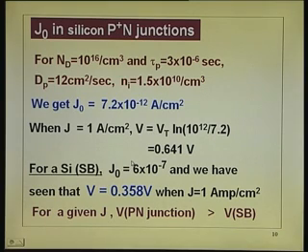So, cut-in voltage is a concept which is used by circuit engineers for convenience, because in the normal range of operation, that is the voltage across the diode. That is about 0.6 volts. That is the implication. So, people who are cautious will say 0.6 to 0.7. That is about the range.